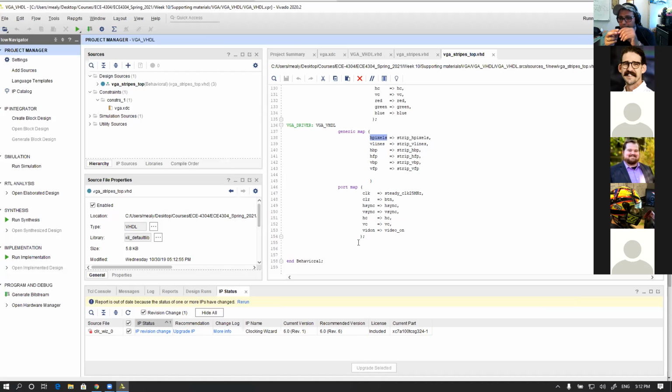Basically, here's the SD card, right? I will take the bit stream now, and I will put it there. Then there is a jumper here. You have to change it to say read from the SD card. Then it will automatically load it from there, and it will not be talking to the JTAG. Especially if you are powering up the board from here, not from the USB.